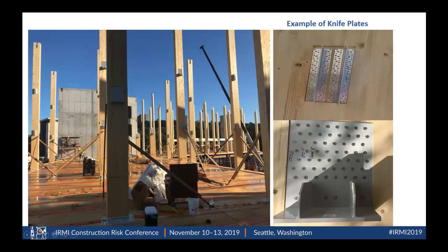Another thing you see here is the 3-story columns. This was done for ease of shipment, but definitely not for ease of installation. We had to battle getting the cross-laminated timber around the 3-story columns and into place. The crews probably wanted to shoot us at times for allowing this to happen, and it's not something that we would do again. Those are a couple lessons learned.